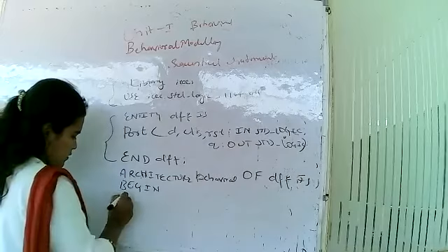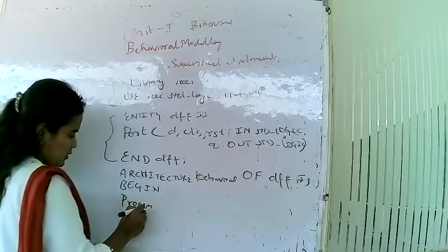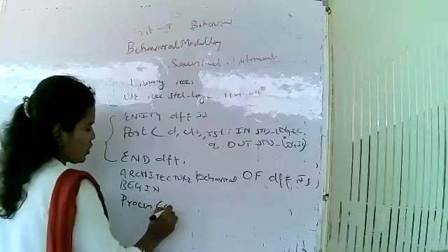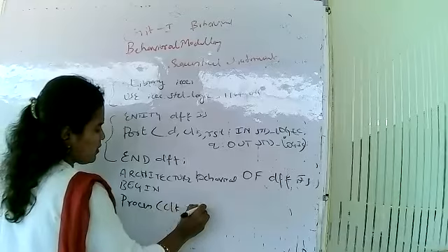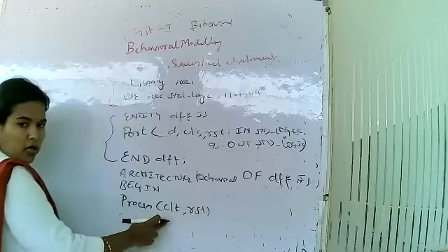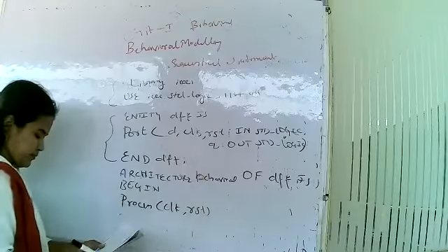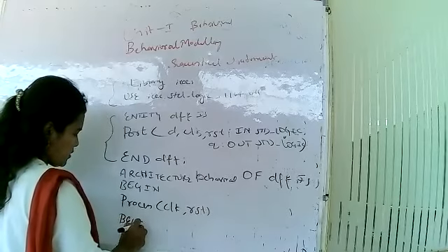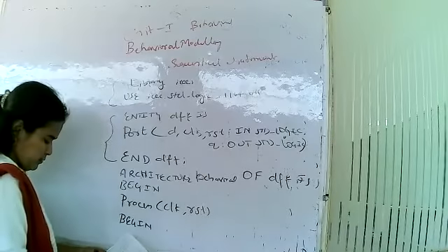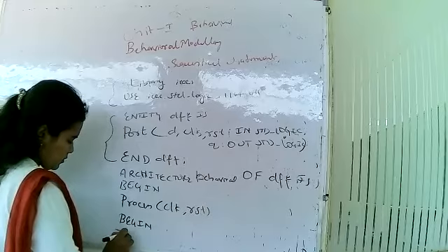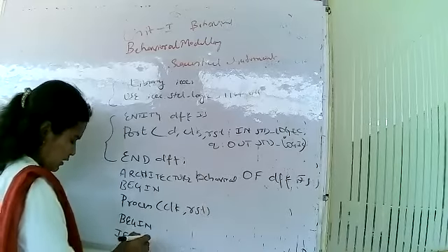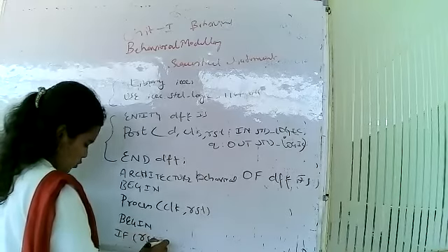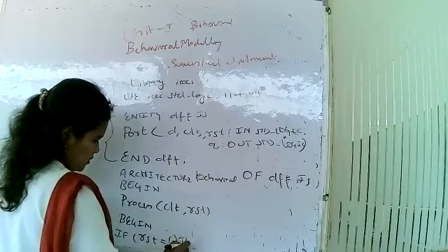Begin process, with clock and reset in the sensitivity list. Next, begin. If reset is equal to 1,